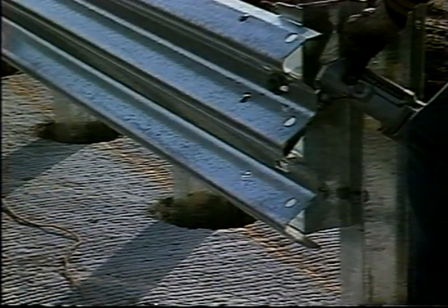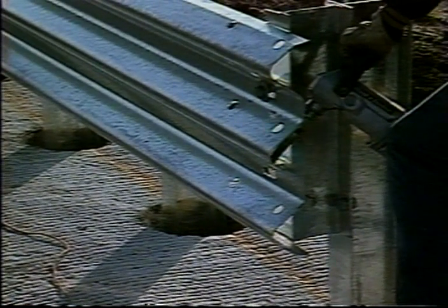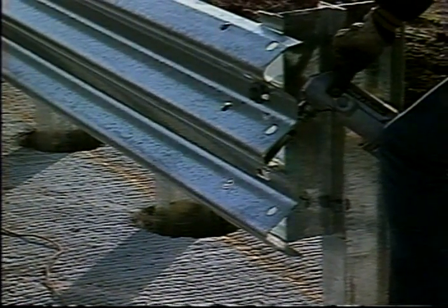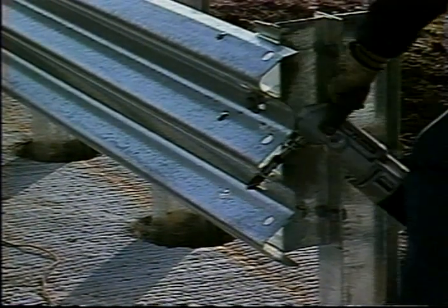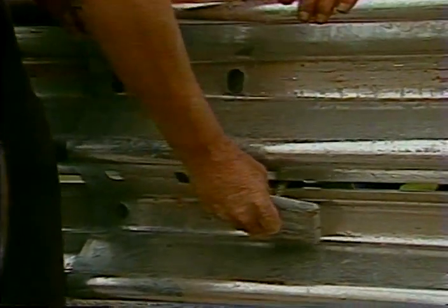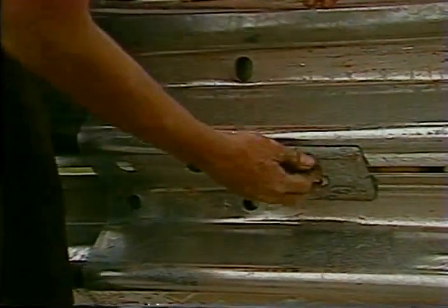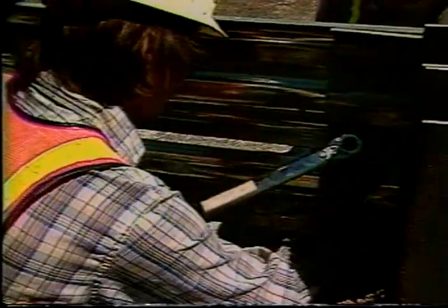A 3/4 inch diameter hole should have been drilled in the transition panel end or the tri-beam guardrail end. If not already done, this hole should be drilled approximately 1 inch from the end of the slot in the fender panel. Place the mushroom bolt assembly through the fender panel and transition panel and secure it with a square washer and nut. Then tighten the mushroom washer nut to 60 foot-pounds. Remember, use holes marked S.